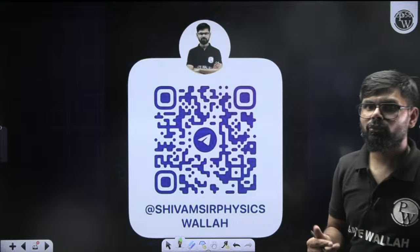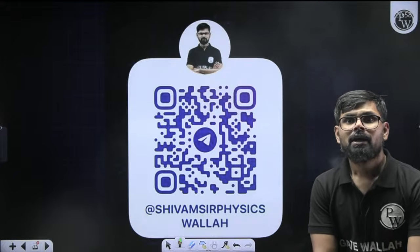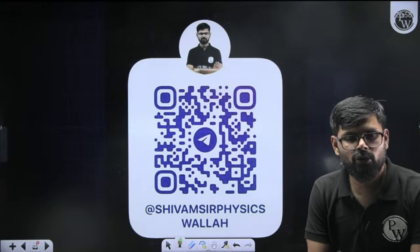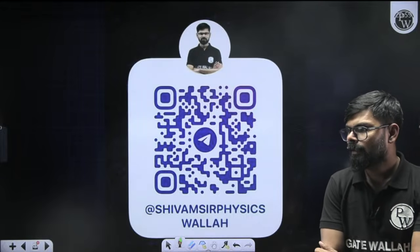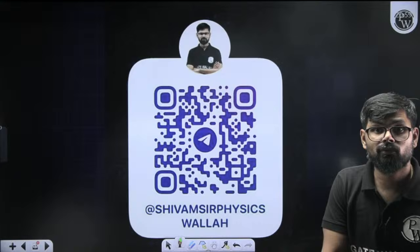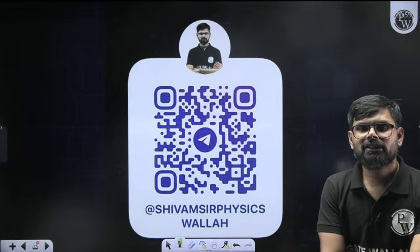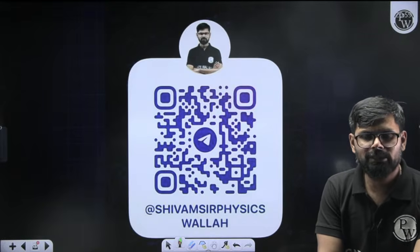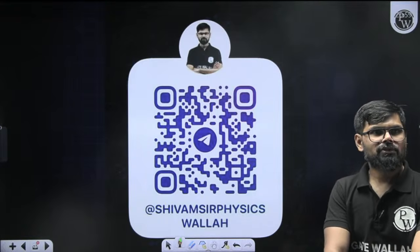Steady flow energy equation is m dot into h1 plus c1 square by 2000 plus g z1 by 1000 plus q dot is equal to m dot into h2 plus c2 square by 2000 plus g z2 by 1000 plus w control volume dot. Clear? Is anything else required? W is equal to minus integration 1 to 2 pdv, but rarely are questions coming from there. Even a question related to w open is equal to minus integration 1 to 2 vdp can be solved with the help of SFE also. That's it. So this is about today's class.